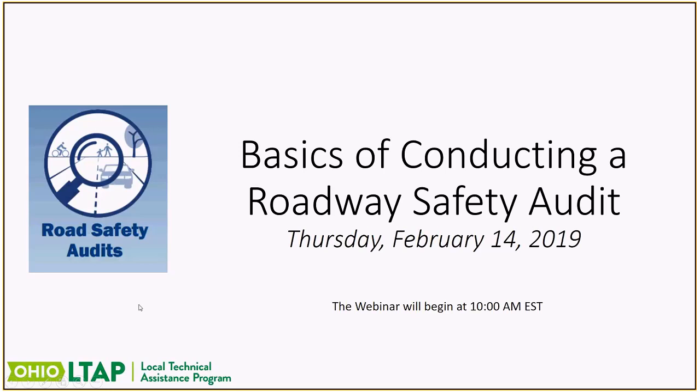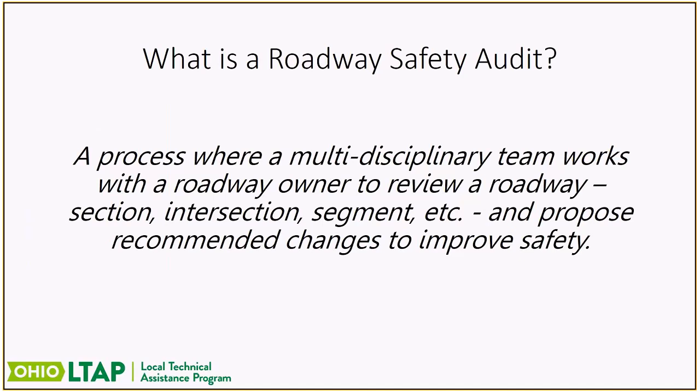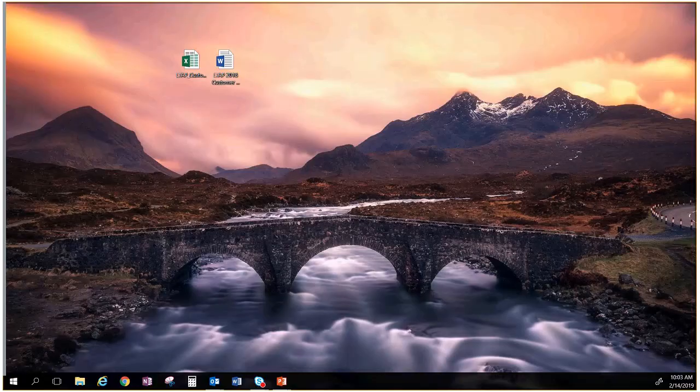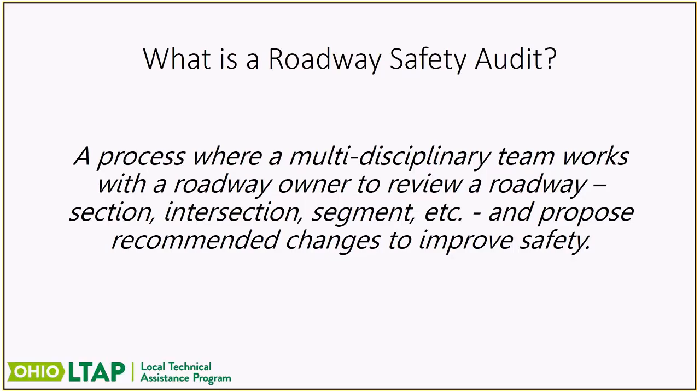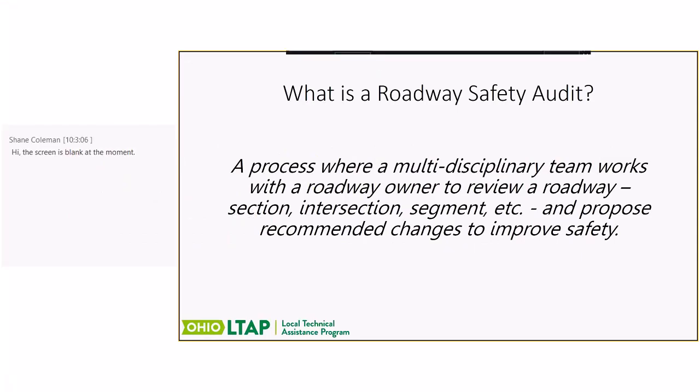Hopefully all of you have heard of roadway safety audits before, but if you haven't, it's a process where you have a multidisciplinary team working with an actual roadway owner to review the roadway, meaning a section or an intersection or a segment, and to propose a recommended change to improve safety. When I say that you're going to review the roadway, a lot of times people will want to include the actual roadway owner, and the process as defined nationally doesn't normally include the roadway owner with the actual team.